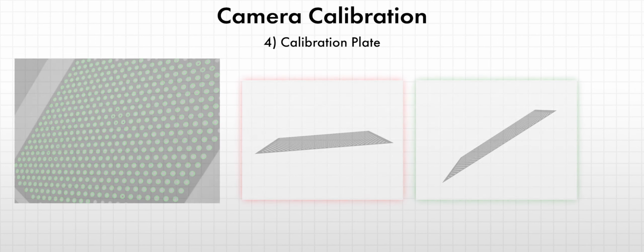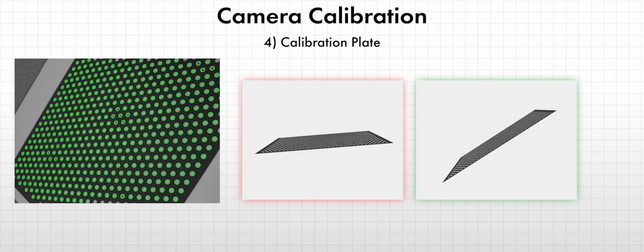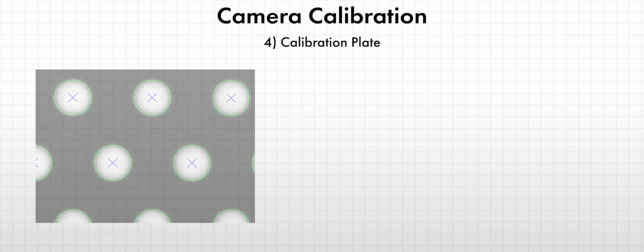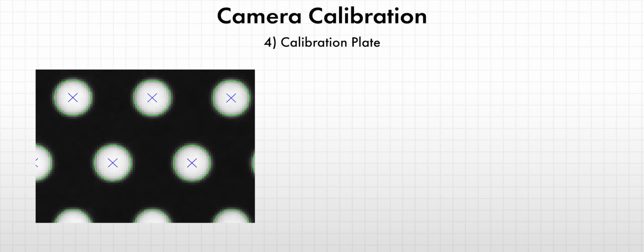As mentioned before, tilting the plate is important for a successful calibration. Depending on the physical space available in your setup, this might require a smaller calibration plate. Additionally, consider that the calibration marks should have a diameter of at least 20 pixels. This might require a larger calibration plate depending on your setup.